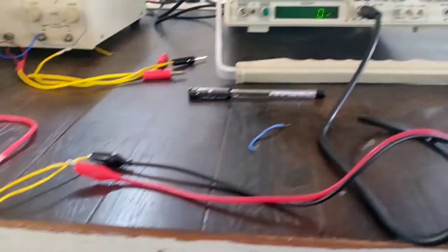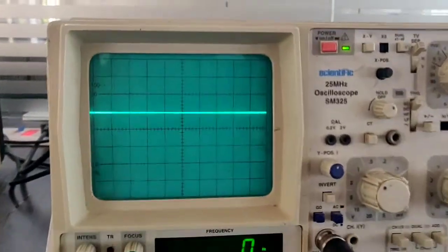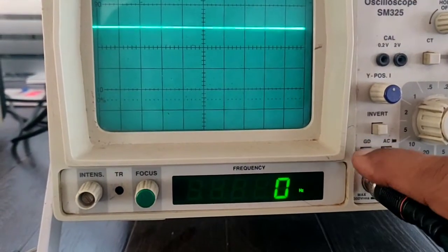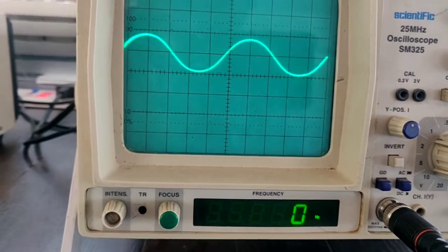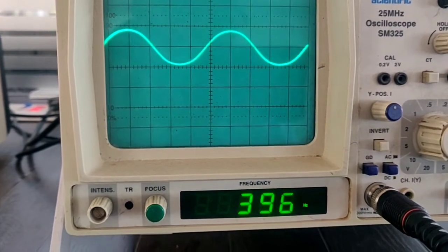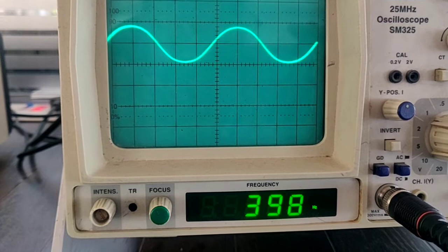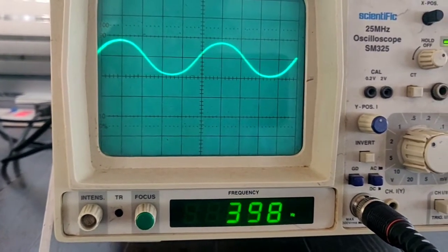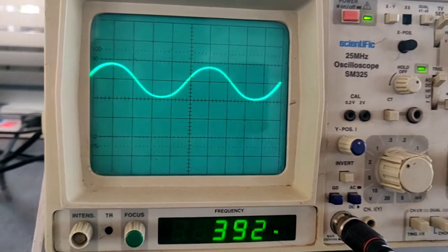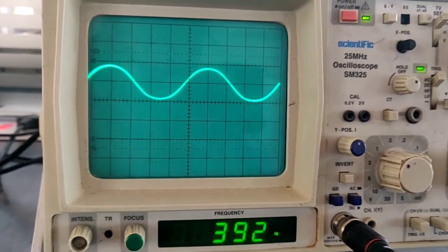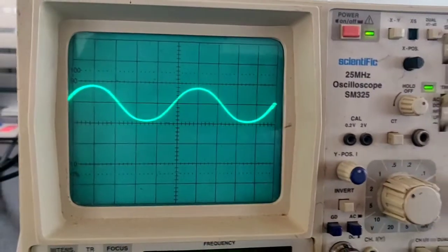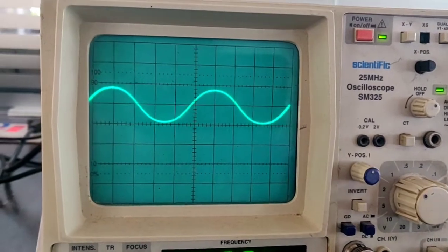I have connected a function generator here, you can see that, but I am not getting output here. Why? Because I pressed the ground key here, so I have to release it. Understand? On most of the CROs, by mistake, when students are sitting idle, they will press all the keys and change the settings. So take care of that. All the keys are released. I am repeatedly telling this because I observe those problems.